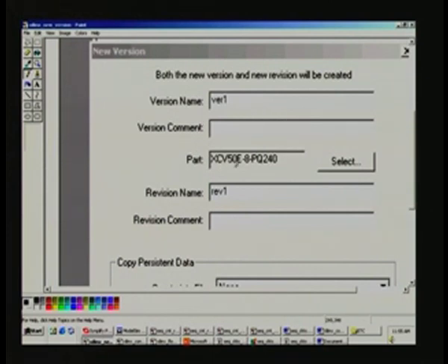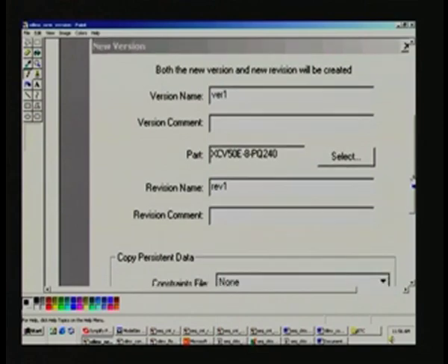Here it is 50E. We can change even at this moment, and the input file for this place and route is going to be the sequential circuits .edf file which we created in the synthesis. In fact, we had come directly from the synthesis, therefore you do not have to specifically mention the input file name. It automatically takes the .edf generated in synthesis as the input file here, and although it is showing revision 1 here, I think it is revision 3 that we are going to do.